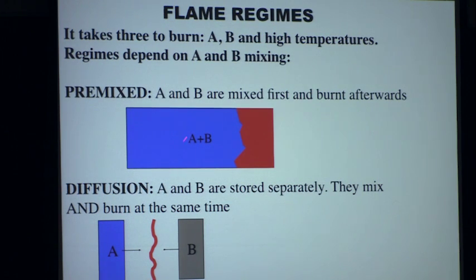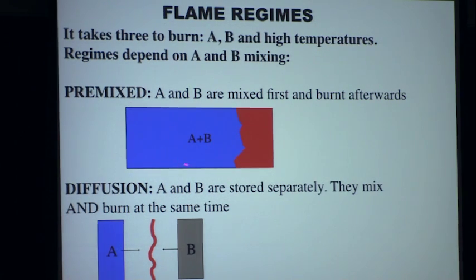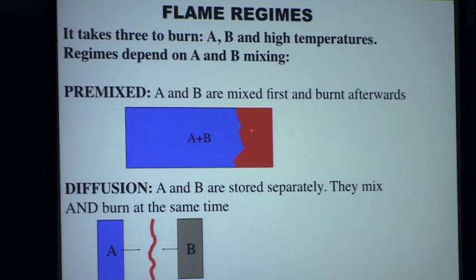Premixed flames is really what Paul is going to be talking about, and I will need to talk a bit about diffusion flames. Those are the basic two prototypes on which we can develop theory and which we need to understand to do combustion. By the way, these flames are much more efficient than those flames, okay? And they are much more dangerous, because if you mix A and B together in a bottle, you just need a spark or any small event, and then everything explodes. So we don't want to do that, except that for efficiency, those flames are much better than those ones.